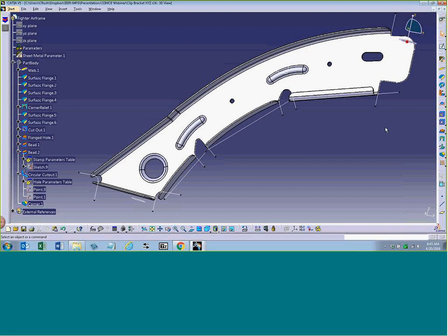So we created interfaces to all sheet metal operations within SEER-MFG that I mentioned to you, and there's much more because we include tooling, drilling, and all the detailed finishing operations. The CATIA interface uses the sheet metal features such as flanges, bends, joggles, stamps, the thickness, the cutout perimeters and outer part perimeters and so on, and uses them within the cost estimate.